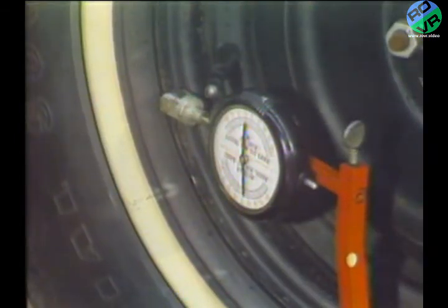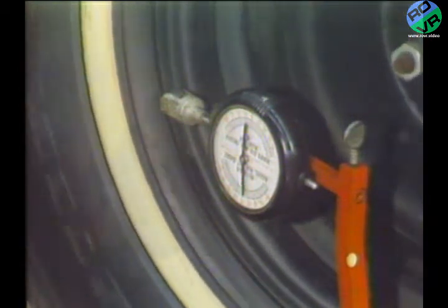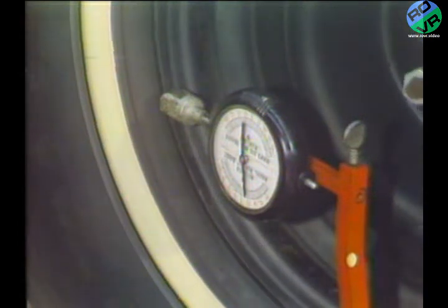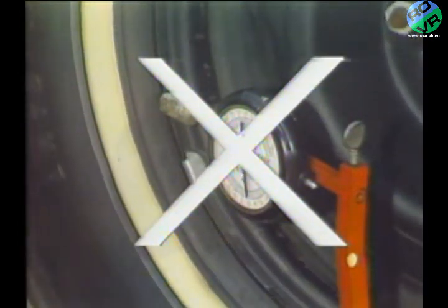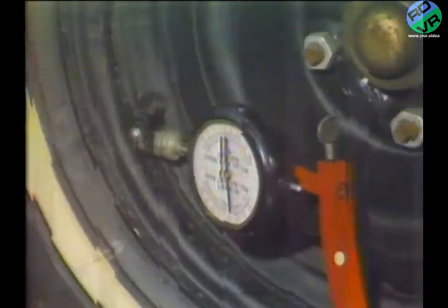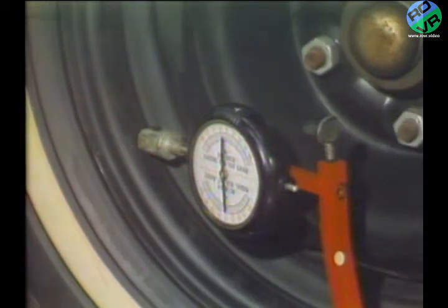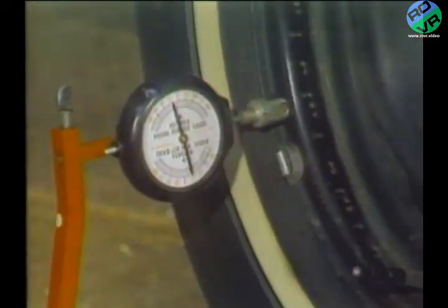When you check a wheel for lateral or radial runout, be sure the dial indicator does not contact the extreme edge of the wheel, because this position will not give an accurate reading. To measure wheel radial runout, place the indicator stem against the flange of the wheel. The indicator stem is now placed in position for measuring lateral runout.